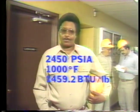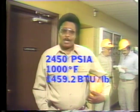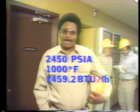We'll use the superheater outlet conditions of a typical boiler to show you how to set up this problem. Earlier, we determined that the enthalpy of steam leaving a typical boiler at 2,450 psia and 1,000 degrees Fahrenheit was 1,459.2 BTUs per pound.